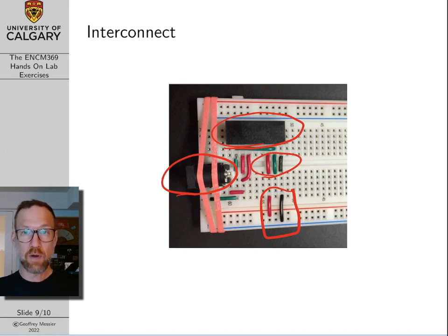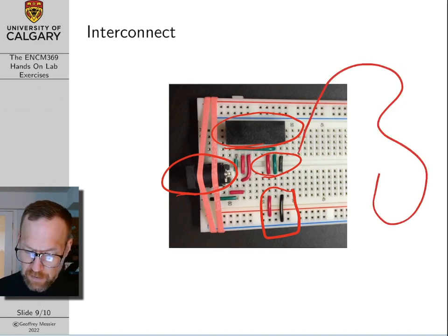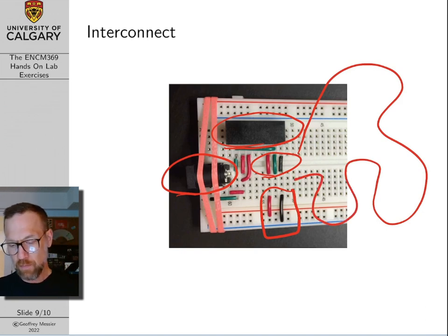This is great for a couple of reasons. First of all, it's very easy to debug. When you've got a big long wire that starts and then snakes out and plugs into another spot in the circuit, you have no idea which wire is connected where. And as soon as you've got large nests of wires, you can brush them, and they'll become accidentally disconnected. This is not such a big deal for our circuits because we're relatively low speed. But when you start to do higher speed digital design, long wires like this can cause you problems by making your signals really noisy. So use short wires.